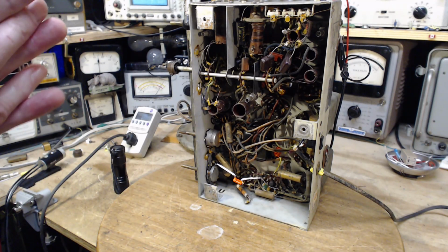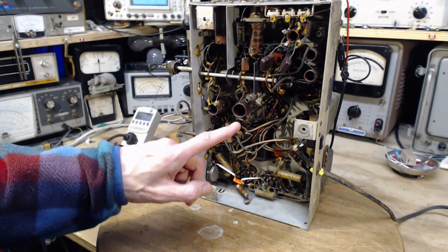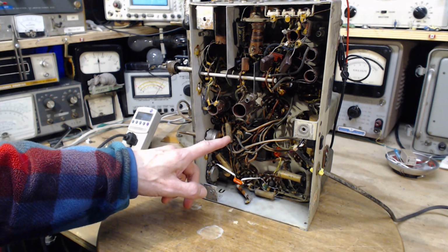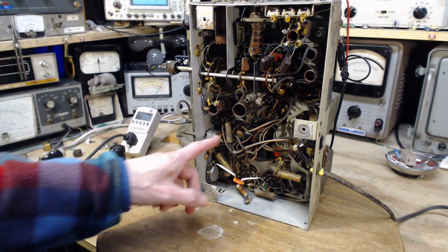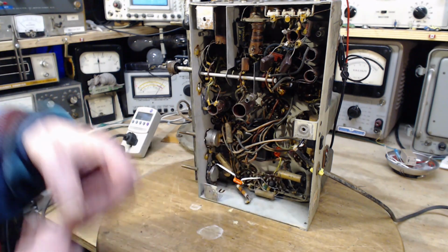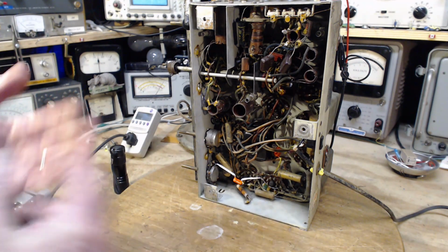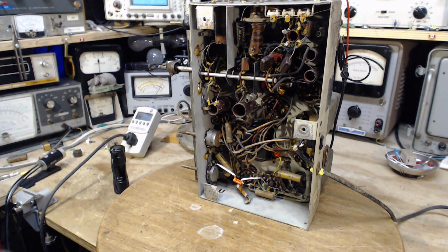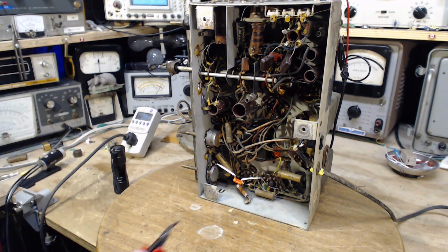Okay, why don't we cut this capacitor out, make sure about its size, test it, see what condition it's in. Then we'll put the substitute capacitor in with the substitute box, set it to the same size as this, operate the set, then we'll vary the size and eventually disconnect it entirely and see what we hear coming out of the speaker. My prediction? We'll never hear anything unusual while I'm doing this stuff. That's my prediction.